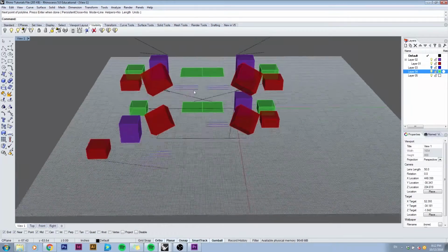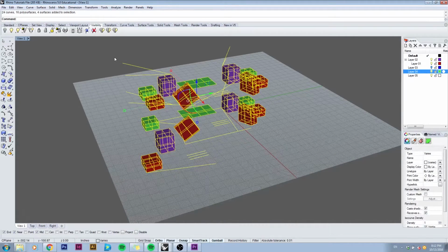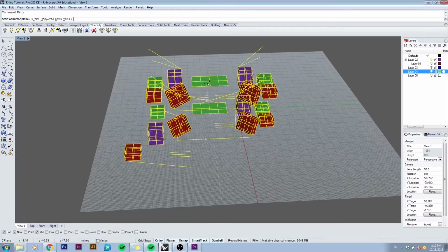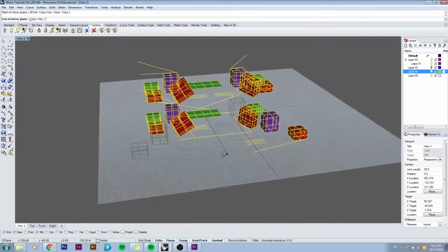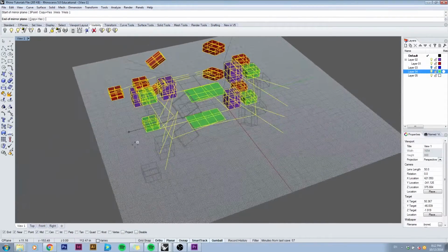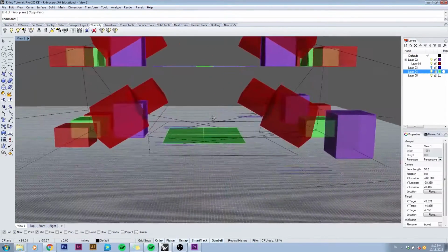Let's try to duplicate all of my current geometry and create something more messy and complex. I'm going to select it all, type in mirror. Now I'm going to try to use Smart Track to snap to what I know is a sort of symmetrical line happening here in my model. And actually I'm going to try to turn it 90 degrees. Mirror at 90 degrees. Like so. I'm going to click. And now the model is mirrored.